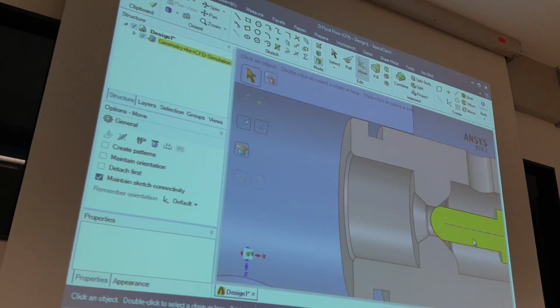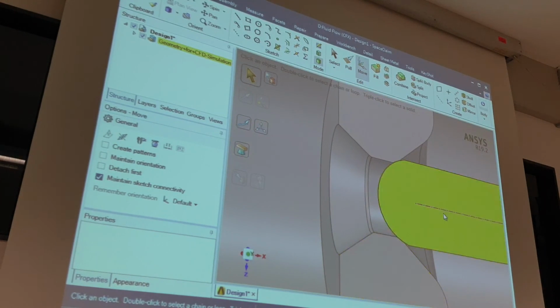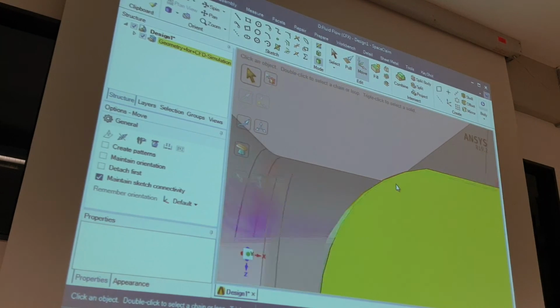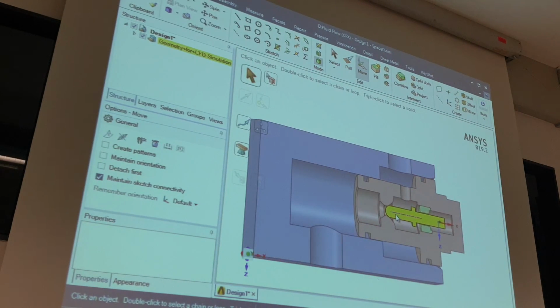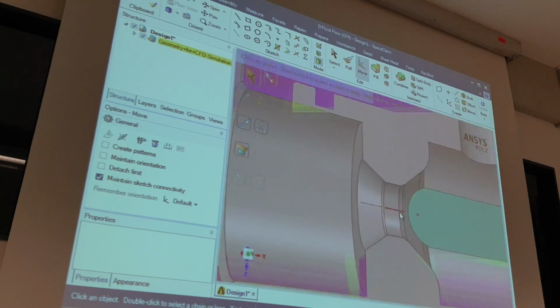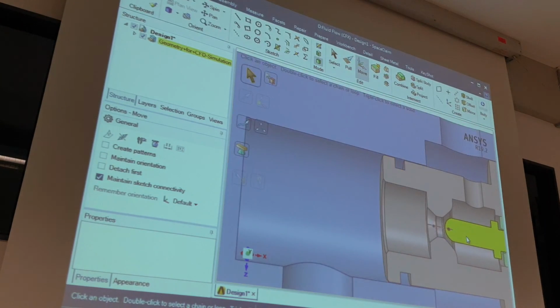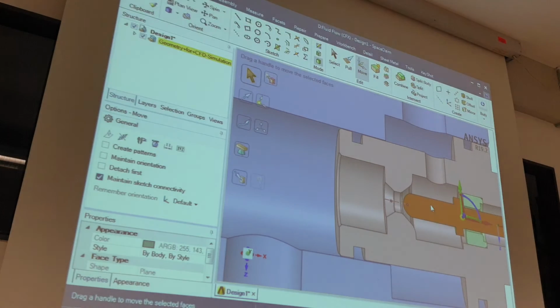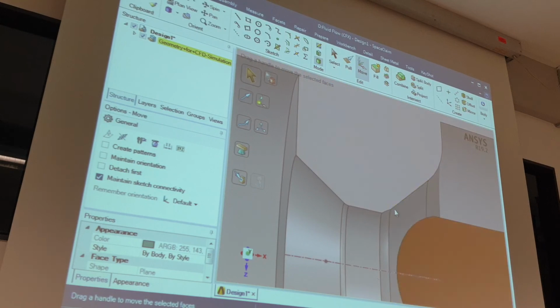And then if you move your pin left 0.5 millimeters, then we have 0 now. And the task is to do the simulation for 1 millimeter stroke. Then I can choose again 3 times the mouse button, and I can move 1 millimeter right, and then I have 1 millimeter open. So, did you understand? I moved the pin half a millimeter left, then I have 0, and then I moved in the other direction 1 millimeter. Then I have 1 millimeter stroke, 1 millimeter opening.